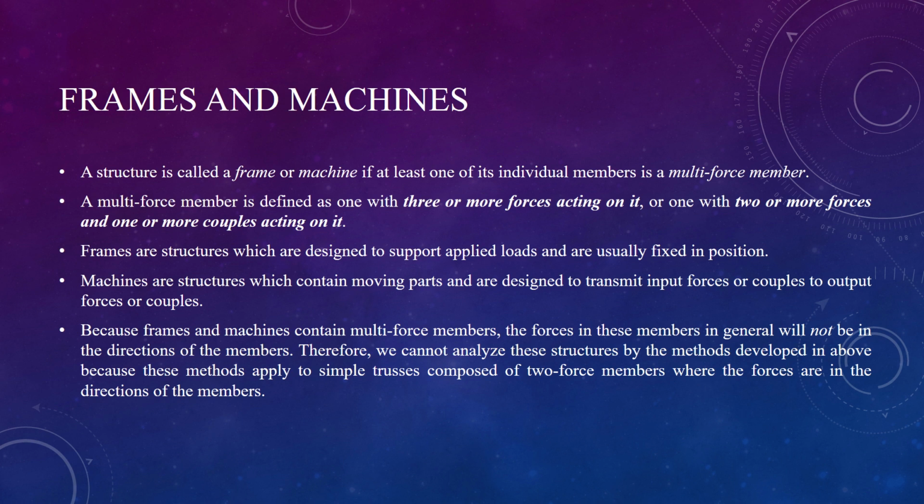A multi-force member is defined as one with three or more forces acting on it, or one with two or more forces and one or more couples acting on it. Now, frames are structures which are designed to support applied loads and are usually fixed in position. Machines, however, are structures which contain moving parts and are designed to transmit input forces or couples to output forces or couples. Because frames and machines contain multi-force members, the force on these members in general will not be in the direction of the member